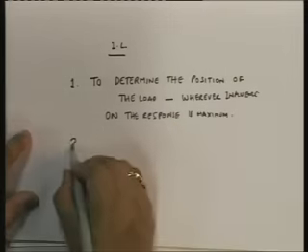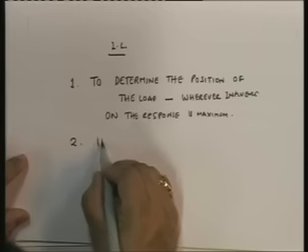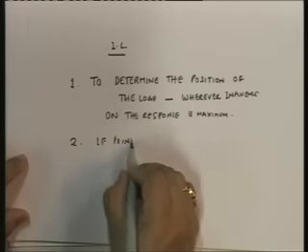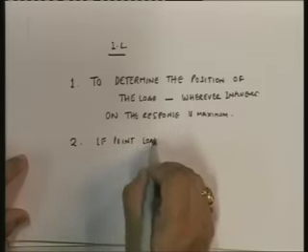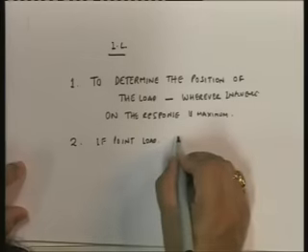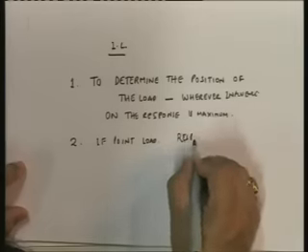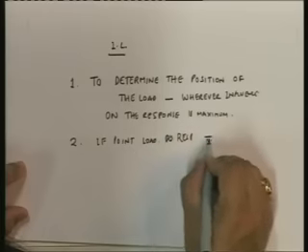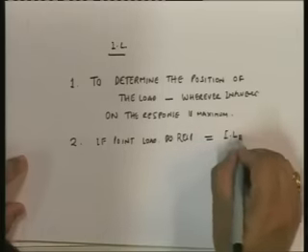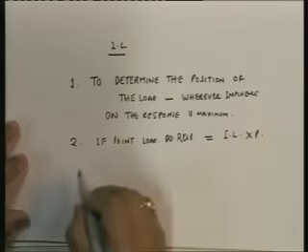Okay, and once we determine the position, if it is a point load, then the design response is equal to influence line into load.